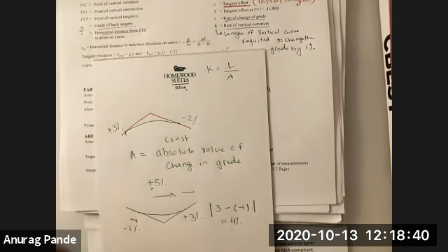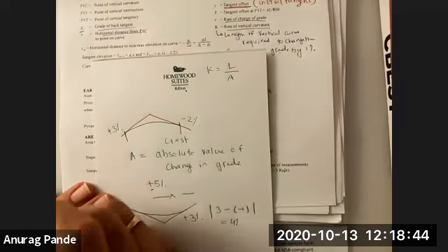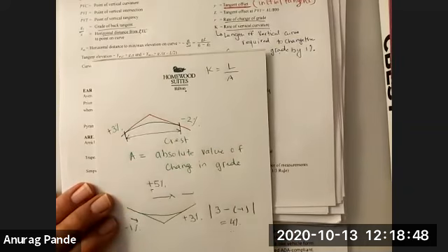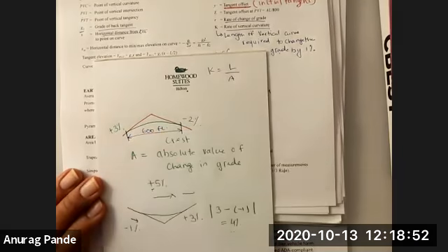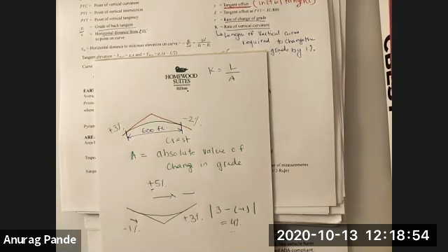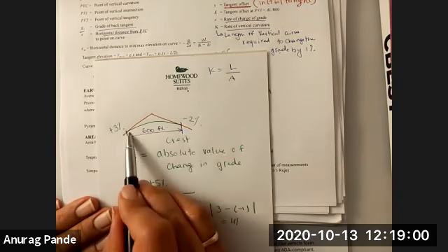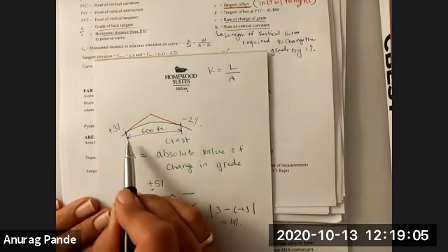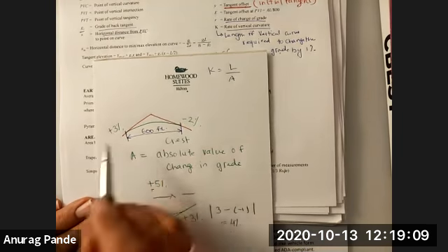Remember, I told you that the length of a vertical curve is defined along the horizontal plane. Let's say the length of this curve, just to take a quick example, is 600 feet. What is happening in this curve is a change of grade from plus 3 to minus 2, so you're changing the grade by 5% over a length of 600 feet.